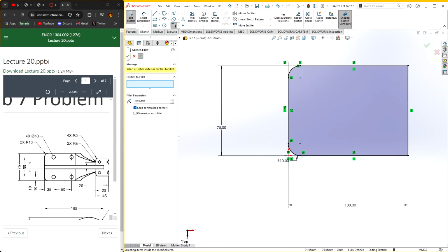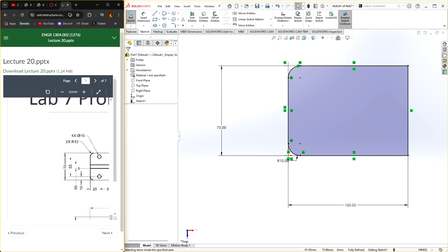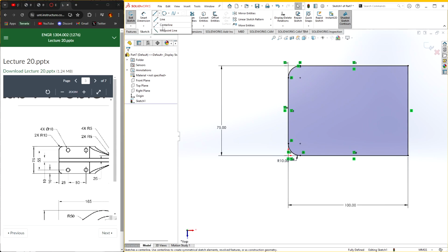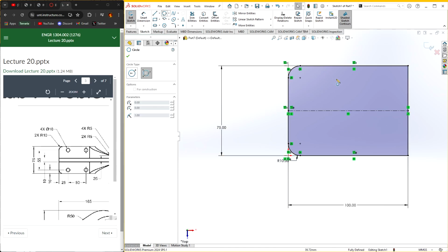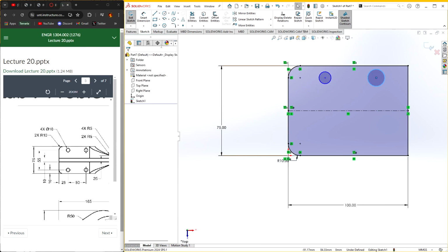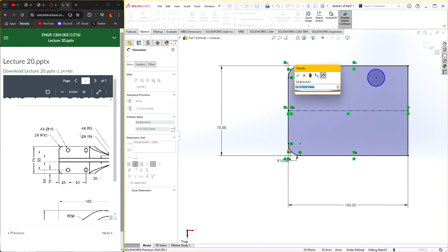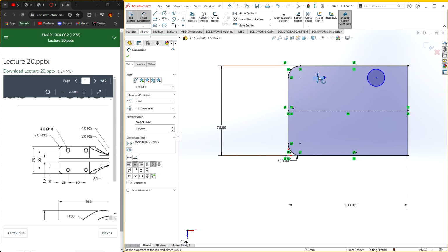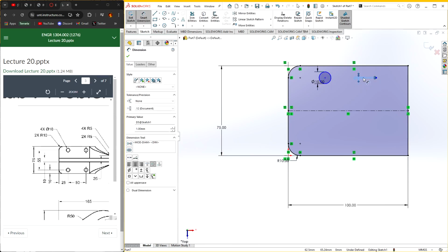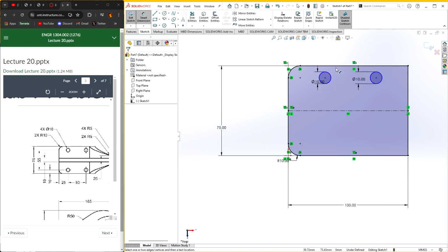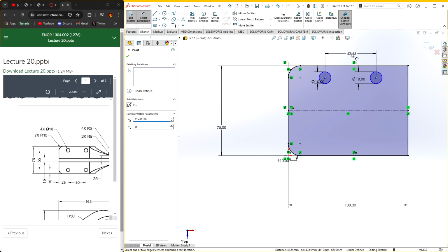Alright. So with here, now we just need to make these holes. So I'm just going to make a center line from the midpoint to the midpoint. Like that. I'm not going to use perimeter circle, I just want a normal circle. So these need to be set to 10, that is 10 millimeters diameter for both. I keep saying it as 1. Hold up, 10, there we go. Okay, the space between this point and this point should be 50.